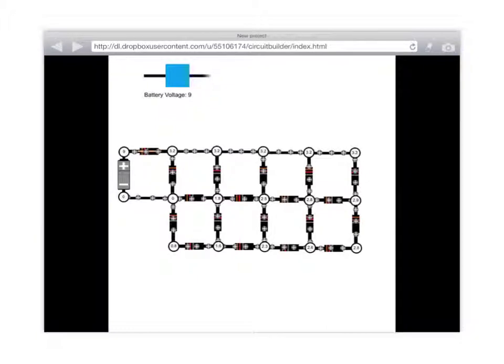All right, so let's point at some specific ones. Can you guys read that number? 9. That's 9, and this is 0. This is 9 to 3.2, 3.2, 3.2, 3.2. Why are these all the same? Why are these all at 3.2 volts across the top? They're all connected.